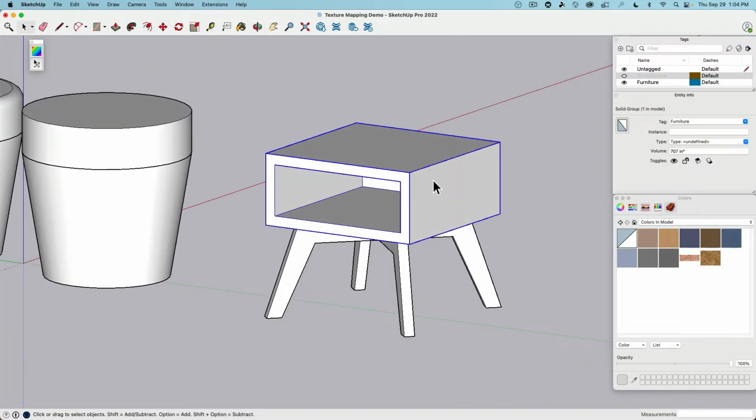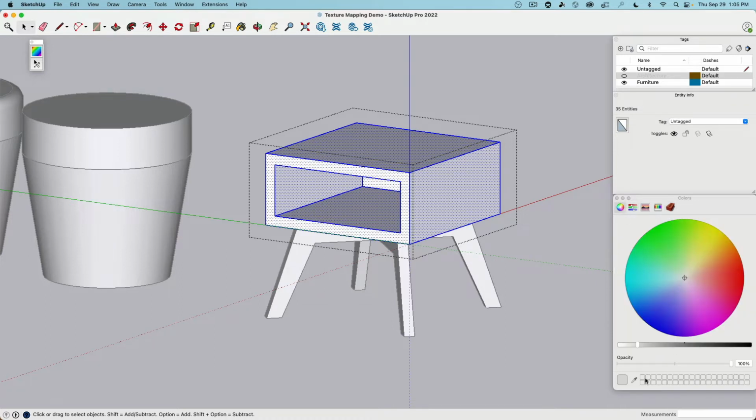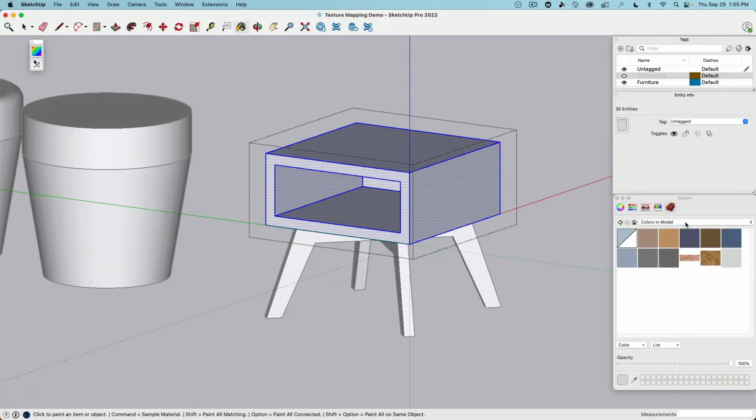So the main carcass should be white furniture paint. The front face should be layered plywood, and the legs should look like real three-dimensional wood. On the Mac here, we'll go into edit group, select everything. Then I will go to new, like the color wheel. I will pick myself a color, and then I paint this, and this kind of created the material for it. Or we can just right click new texture.